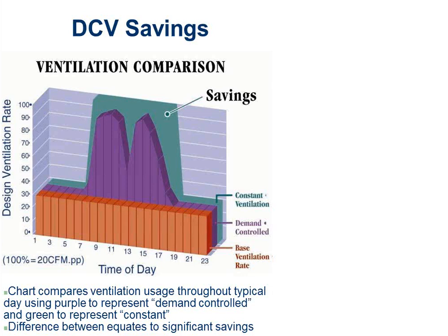But on a rooftop, the rooftop doesn't know it's night or day. It just knows the fan's on. And if the fan's on, it goes to ventilation position. So that's why we're showing it like that with the green bar here. Some systems may go all the way off. This one's a little bit different because it's a rooftop type job.